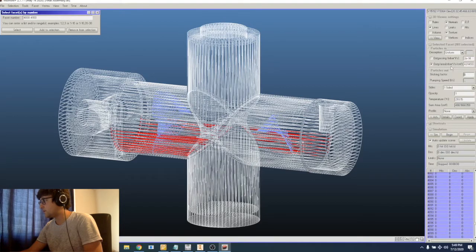No, per centimeter squared, my bad. 2e minus 14. So now, you can either do outgassing rate per area or just a straight outgassing rate. I just happen to know the rough outgassing rates per area of some heat-treated stainless steels. So I'll apply that. So now it'll desorb.